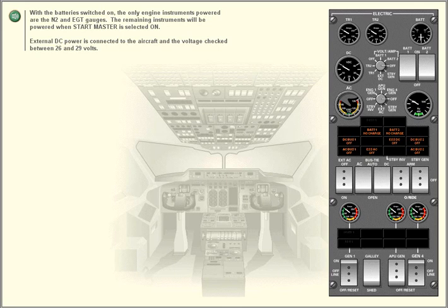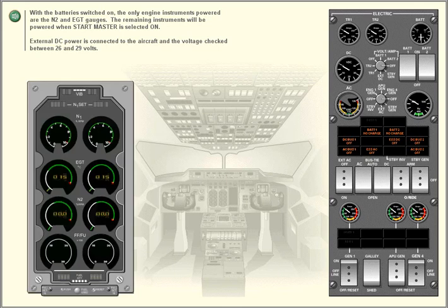With the batteries switched on, the only engine instruments powered are the N2 and EGT gauges. The remaining instruments will be powered when Start Master is selected on.